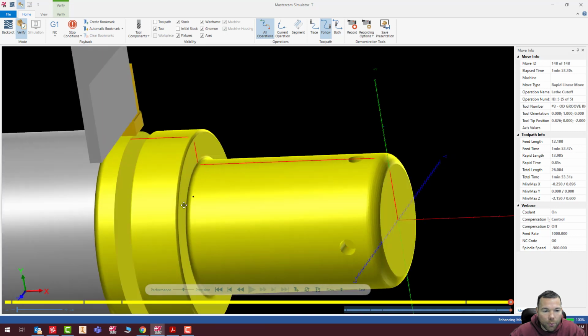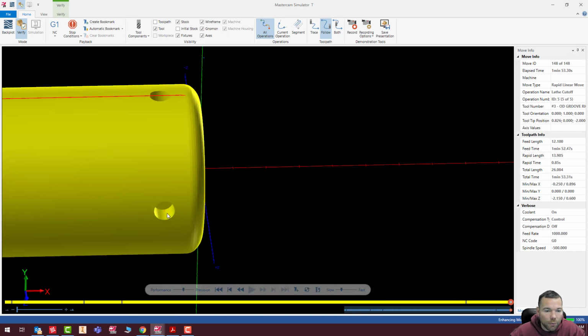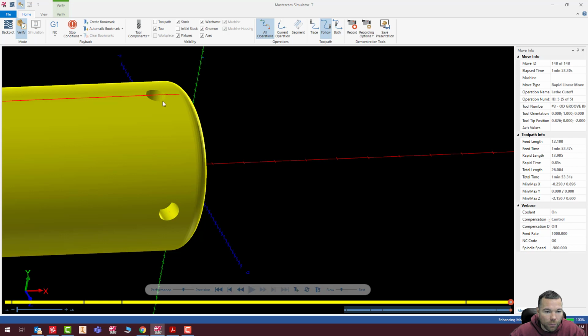So it's pretty much completely deburred, with the exception, of course, of us putting some chamfers on there, which we could very easily do. Your book doesn't have you call for it, so I didn't really go through it. But all you need to do is repeat the drilling process. Just select a chamfer or a countersink and just figure out what your depth needs to be.